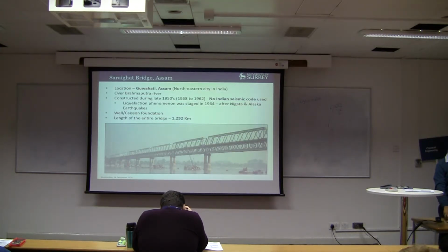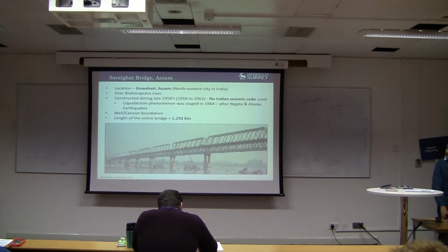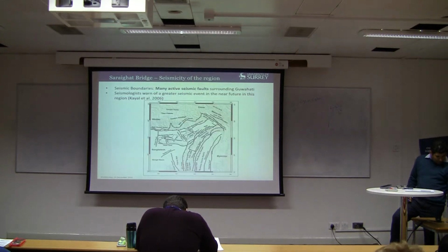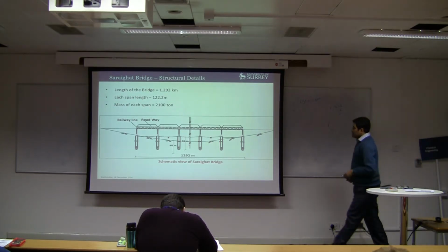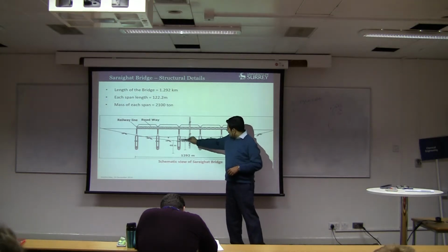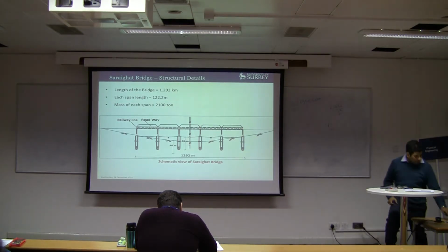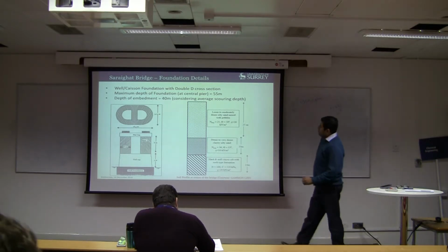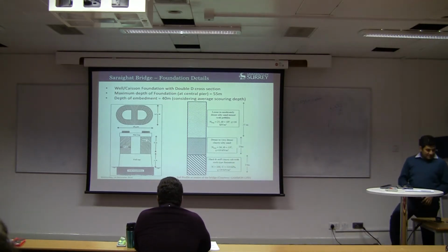Another interesting example is, if you have a large diameter, you don't see these issues. Just to bring you back, that particular bridge has quite a large depth, long span, and a very stiff foundation. And therefore it just collapses. Those foundations were very, very large. And if you have a big foundation, the time period doesn't increase.